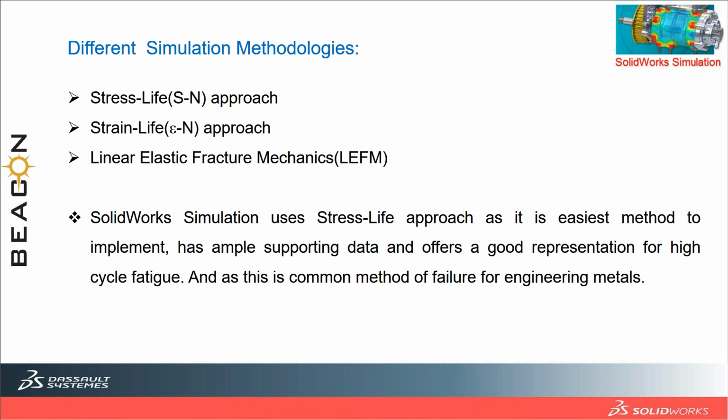Whenever you go for fatigue analysis, there are different methodologies available in the market. We have the stress life approach, the strain life approach, and linear elastic fracture mechanics. Here, in brief, I'll describe what we mean by the S-N curve and S-N approach, the strain life approach, and linear elastic fracture mechanics.